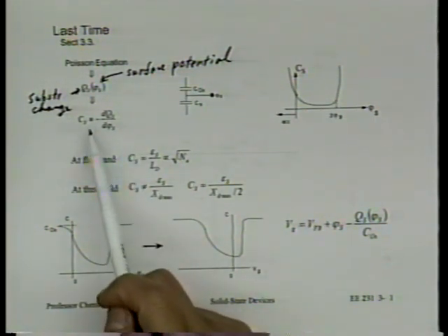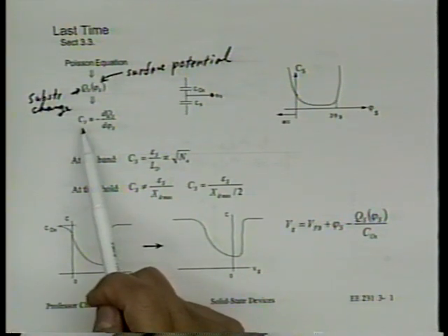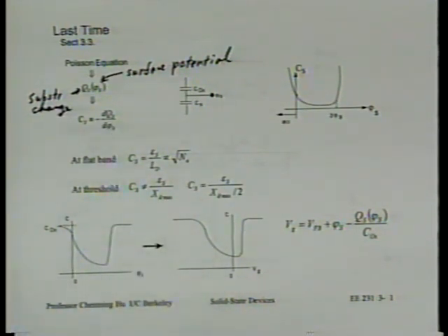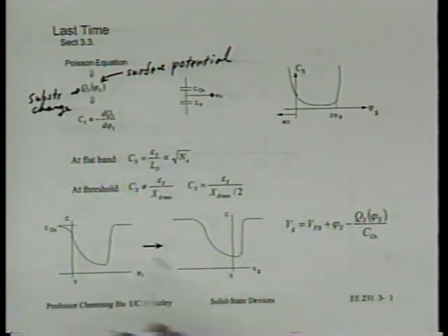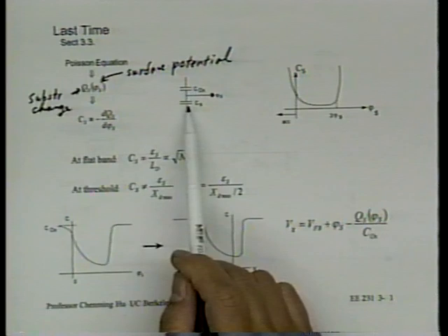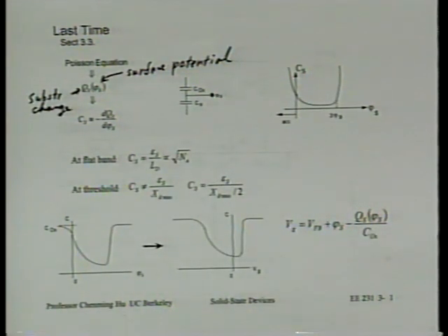Next, we use the relationship that the small signal capacitance of the substrate is equal to minus dQS d phi s. Now, this may need a little bit of thinking, getting familiar with this concept that indeed there's a capacitance between the interface and the neutral body, and that capacitance is called CS, and it involves charges contributed by the inversion layer, depletion layer, and accumulation layer.